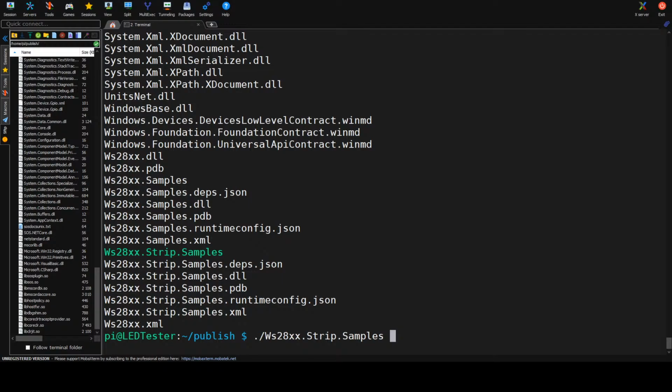From the hardware side, you'll need to hook up the LEDs. So you'll have to have a power source for the Pi, a power source for the LEDs, and then the MOSI and the ground pins for the Raspberry Pi, which I just screwed up mine trying to hook them back up.